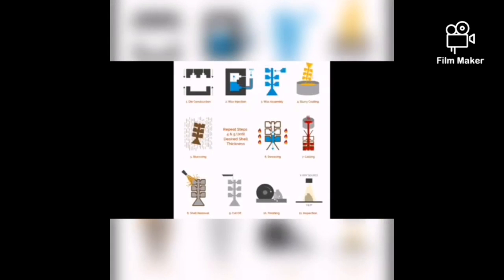The other process to make titanium alloy is investment casting. First thing we need to do is create a wax pattern using the 3D design model with AutoCAD, and then the wax patterns are assembled onto runners into a finished tree which is ready to be dipped. And then after the slurry coating is done, particles of sand are dropped onto the surface of the wet tree assembly. This helps to thicken and strengthen the layer of coating on the wax assembly surface.